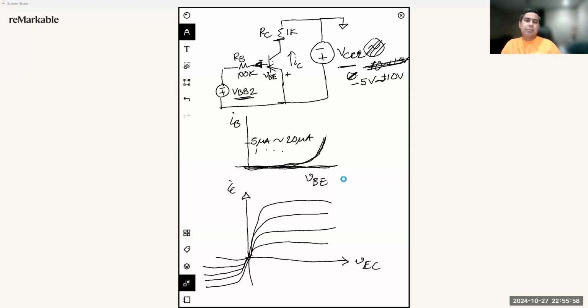So once you do that, you can also, again, build the circuit. The model here for the BJT is going to be 2N3906. It's the same way: you right click on the component, and when the new window appears, you select pick new transistor. And then in the table, you select 2N3906. And that is the device you are also going to use in the experiment to get the experiment done with the circuit.